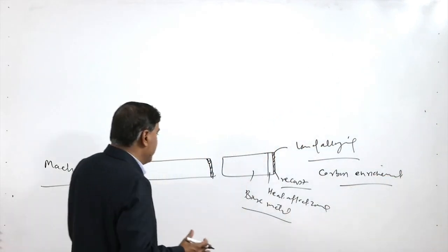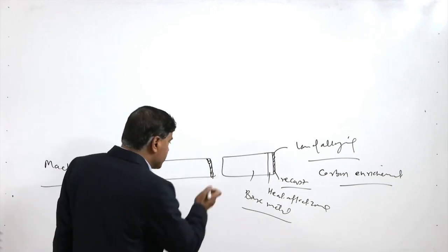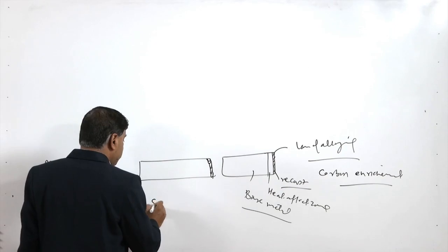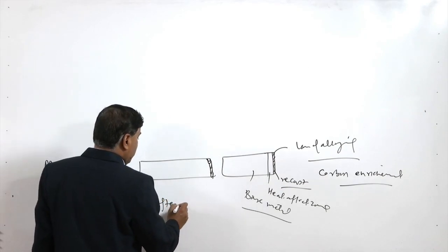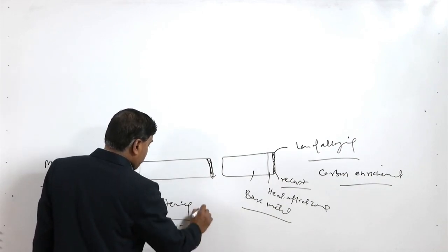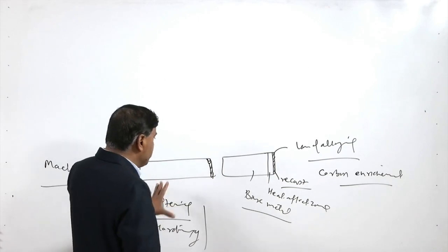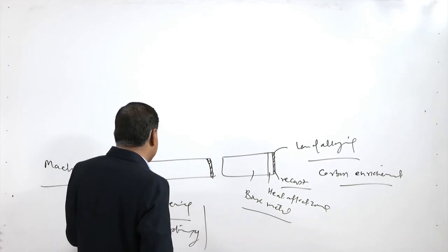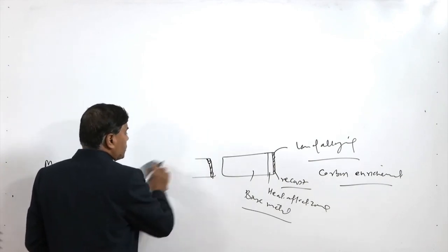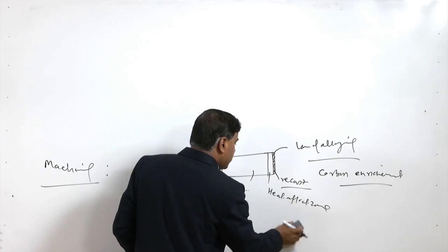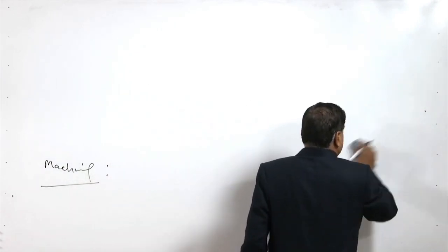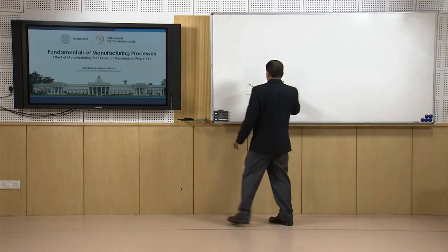As per the strengthening mechanism being used in the given metal, the metal may be subjected to softening due to reversion, or it may be subjected to hardening due to transformation hardening. So, these are the two heat related effects: softening due to the reversion or coarsening of the grain structure, or hardening due to the transformation hardening, related with the material, for the heat treatable systems.